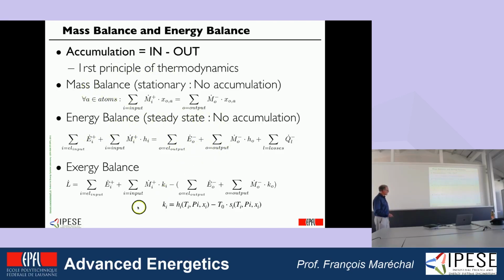And then I will be able to write the mass balance of the system and the energy balance of the system. And I will even be able to characterize the exergy balance of the system by calculating the difference between the exergy that is entering any of the subsystems that I'm considering and the exergy that is leaving the system. The difference being the exergy that is lost in the system. And everything is calculated with the help of the constitutive equations.